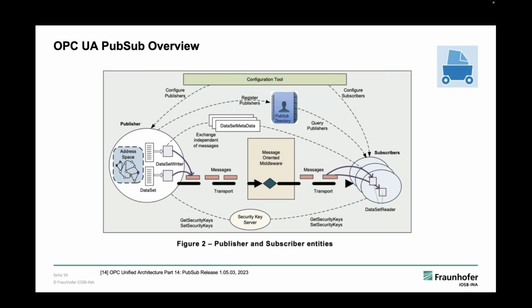So you can connect with an OPC UA client to a server that is also a publisher and configure via this configuration model contained in the server which parts of this server should be published and with which cycle time and so on. And of course, this configuration tool does not have to be an OPC UA client, or this OPC UA client can be contained in some engineering tool. But the point here is you have a configuration tool and a configuration model in the first place.